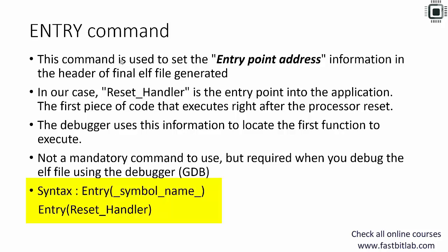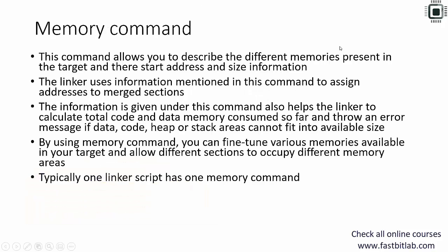ENTRY, and in the parentheses, you have to give the symbol name, that is the function name, which is the entry point into your application. In our case, we are going to write something like this: ENTRY(Reset_Handler), where Reset_Handler is a function name, or you can also call it a symbol. Let's use the ENTRY command, and let me get back to the MEMORY command later.